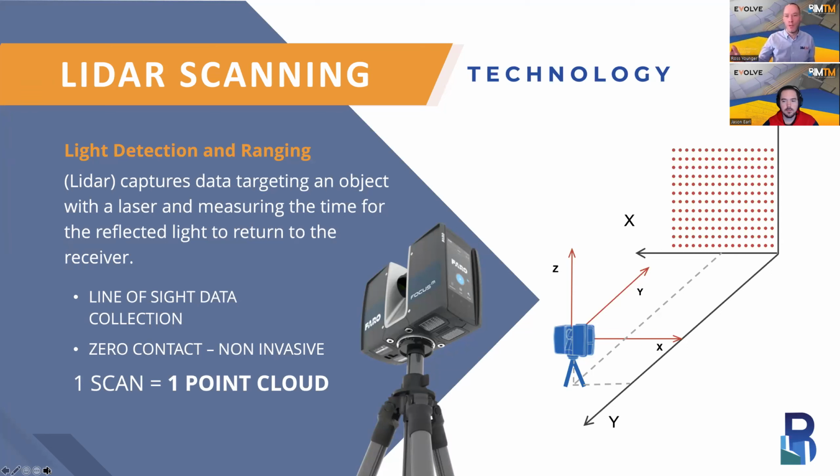And now imagine that essentially what's happening with a laser scanner is that it's methodically rotating and getting about 1 million points per second to document the entirety of a space. These millions and millions of points, when combined, really can provide the overall shape and geometry of different objects. And when dealing with the built environment, especially with very aging buildings, it's a zero contact, non-invasive method of documentation, which is very useful.